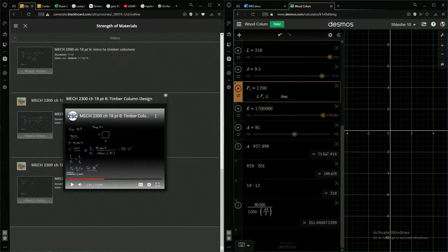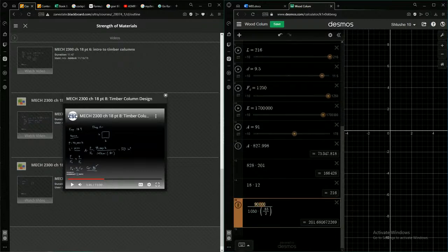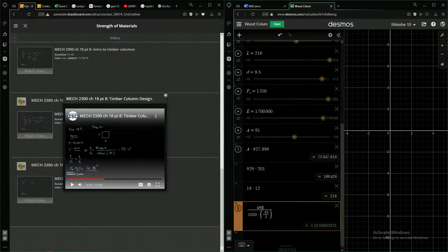So I have a large equation down here at the bottom. We could just type in 48,000. This number here gets changed. We're gonna keep this number so it's a good guesstimate, and we got 90 spit out. So we need a beam with an area of at least 90 inches. So I think a 10 by 10 is really close to 90.